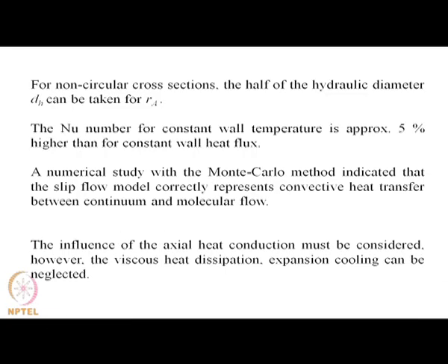So, the other factors which we need to know are that the Nusselt number for constant wall temperature is going to be different from that of constant wall heat flux, and a numerical study indicates that the slip flow model correctly represents convective heat transfer between the continuum and the molecular flow.